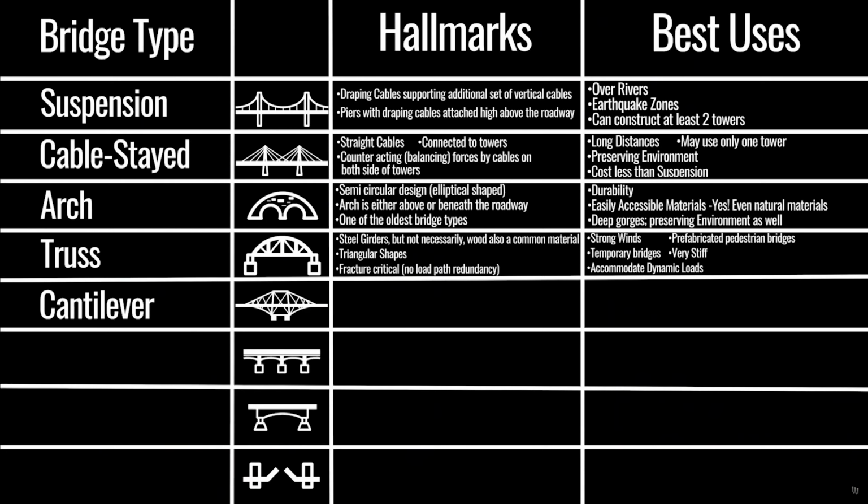And so that's a way to anticipate the fact that when loads go on and we put these beams in place, the loads are going to want to make the beam deflect downward. But because we put what we call camber into this pre-stressed beam, we sometimes are able to achieve no deflection at all at the beginning of installation.